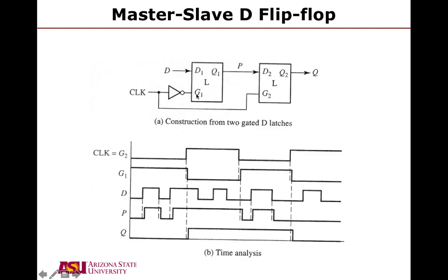And then your clock signals, one's the inverted of the other, to create the rising edges. So if you look at G2 and G1 clocks, what will happen is, if you look at the output signal here, Q will only be tracking the data on the rising edge of the clock. So clock is G2, and if you look here in the top waveform, when it rises, the data is high, D is high, so you can see the output with just some small delay goes high, Q goes high.